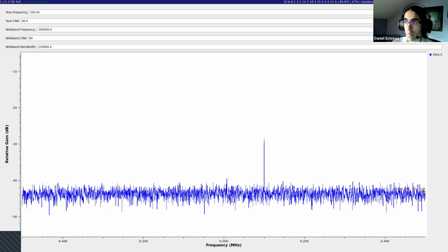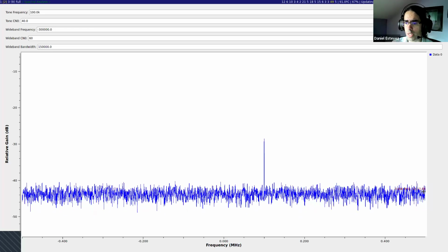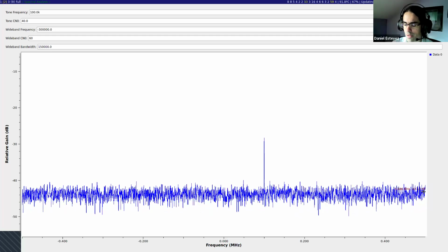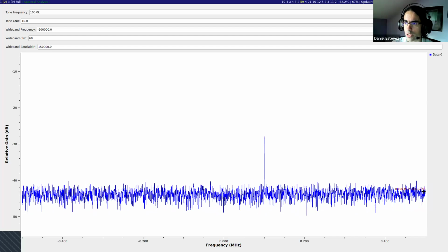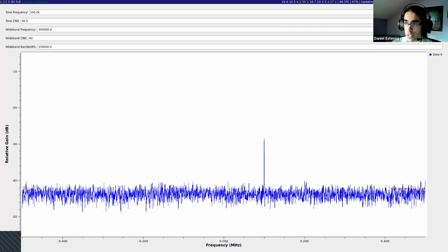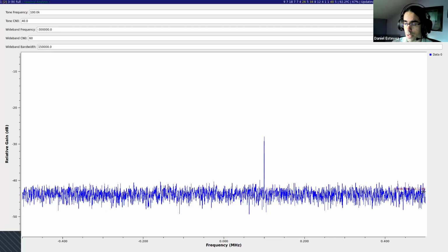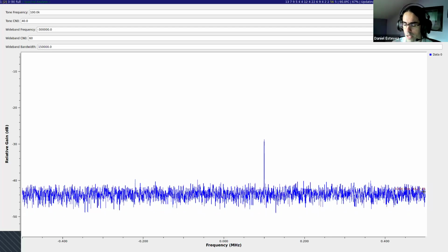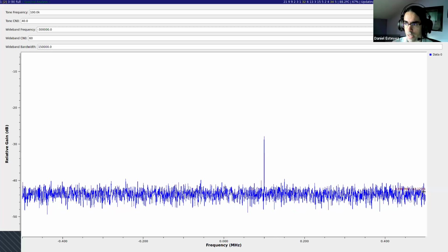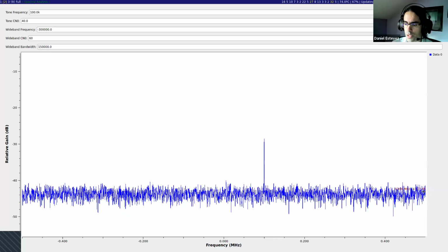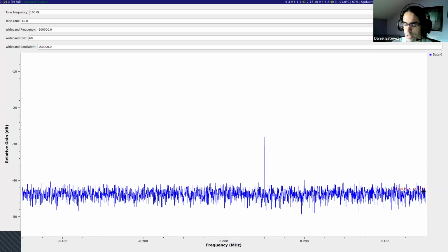And then you say, well, my noise power is something, I don't know, 7, whatever the units are. And then if I want to know the noise power in 1 hertz, I need to divide by 1 million because I'm doing 1 megahertz, which is 1 million hertz. And you do 7 divided by a million. And that is how you know what is your noise in 1 hertz.